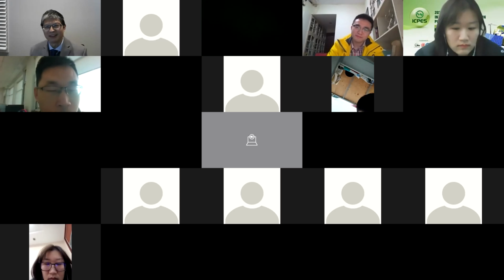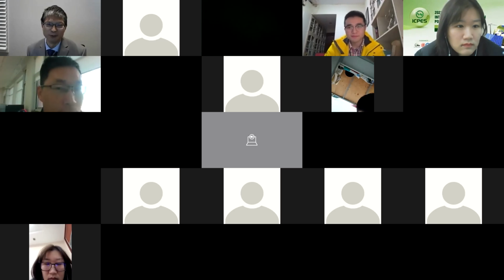So there's a certain distance, an optimal distance, that has to be optimized. I cannot give you a number because it is based on the size, the power level, and the topology you choose, like whether you choose a simple SS combination or you want to choose LCC. But the longest distance, I think you shouldn't go more than a few tens of centimeters. As a rule of thumb, the size of the transmitting and receiving pad should be 2.5 times the distance. Okay, so that's a rule of thumb.